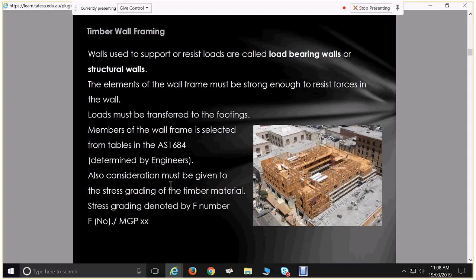So a very common specification for timber, and I'll actually write this down, or try to remember this, is for all of your exposed stuff, you use F7 H3 LOSP. Now that's a good one. With pretty much all the drawings I do specifying timber, the engineer would be writing F7 H3 LOSP for all the external exposed elements. And that's going to be, if you're buying a post for your veranda, a piece of fascia or so, it's going to be primarily F7 H3 LOSP.